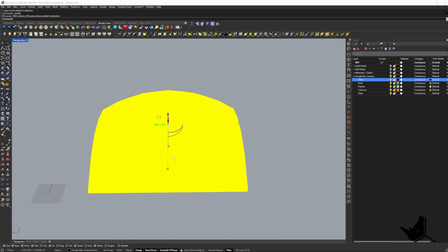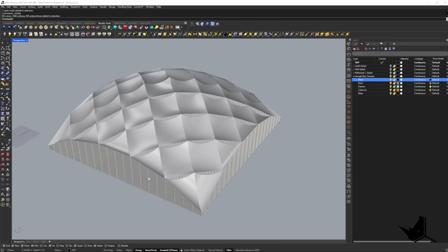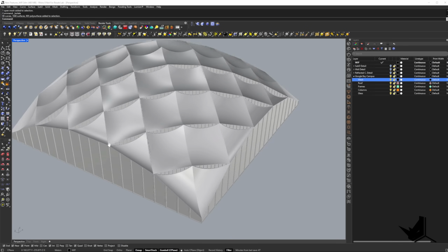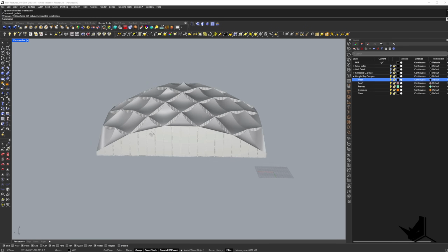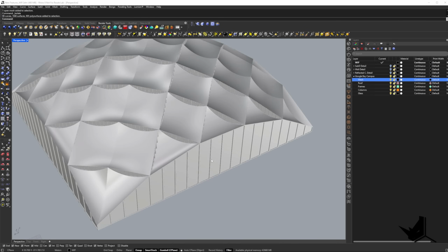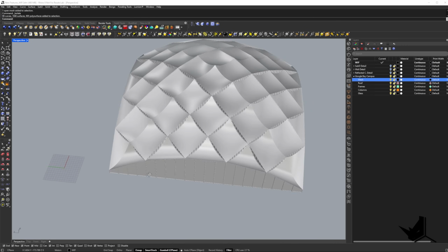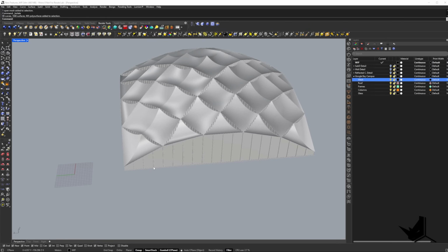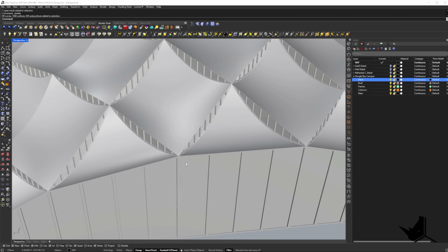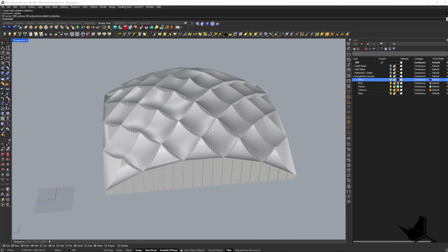This is of course a very heavy file. It has around 800 megabytes, but you can see that we have all of the details for the windows and all of this. So now you can of course take this to your 3D printer and you can expect to get all of these details in. One thing to note is that sometimes you may want to increase the size of your file to scale it up so that you can do this manipulation, then scale it down to the size of the 3D print bed.